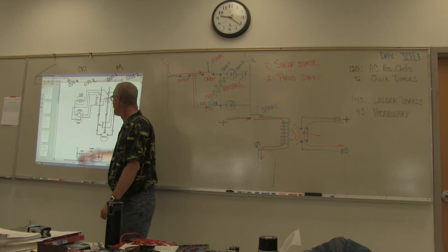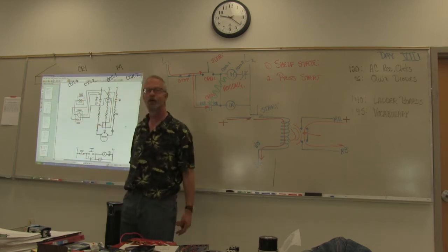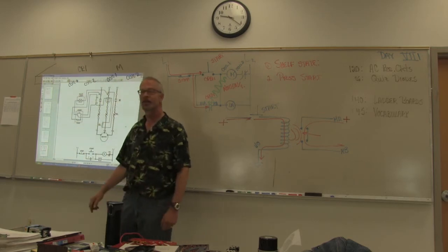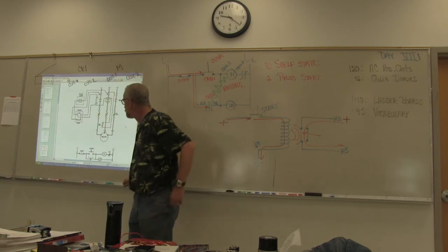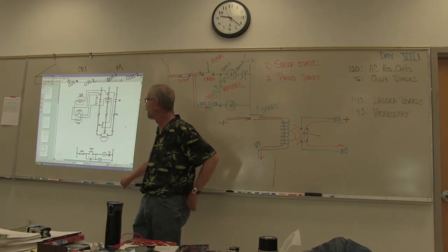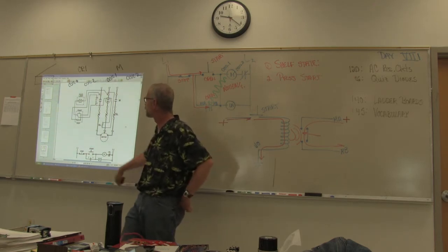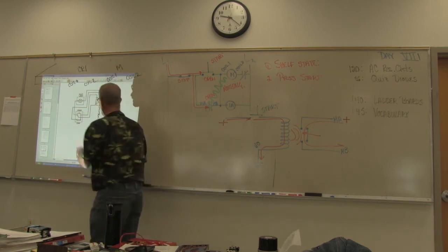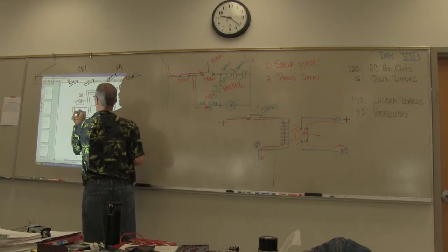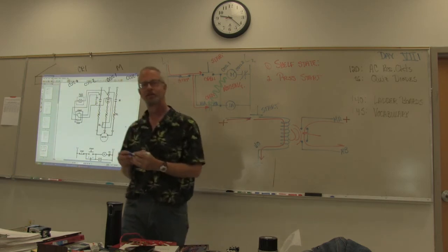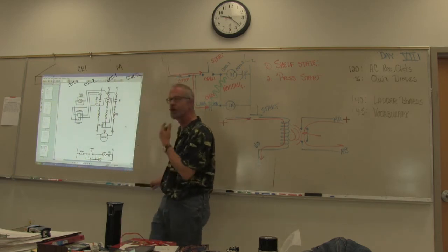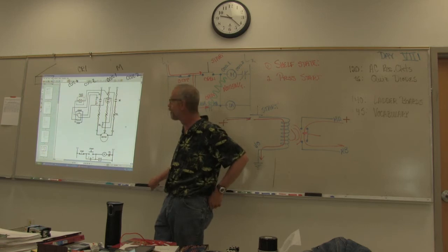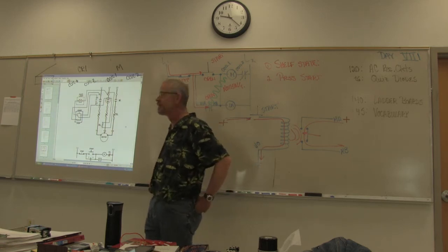You'll also notice that these do not follow what we talk about in our 104 class. Since when did we start using dashed lines to represent object lines in a drawing? It's showing you that's a control box. You have to look at what they are trying to get across here. The reason they don't use solid lines is because they're using solid lines for the circuit traces, and it would be very confusing to have a solid box around here. How are you going to separate those from each other? You do what you have to do to make things work in some cases. Sometimes what works in one industry doesn't always work in another industry. And when it comes to drawings and schematics and ladder logic, that is the case.